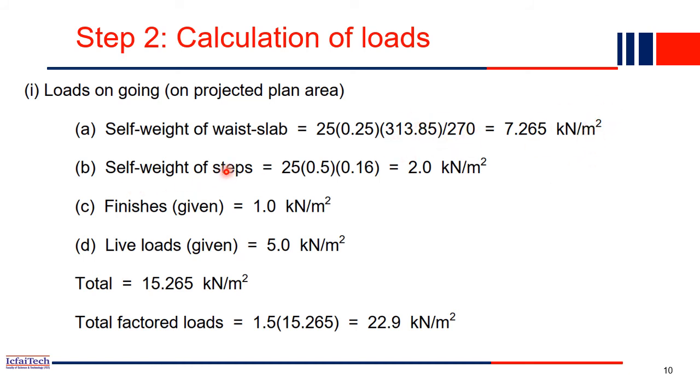Now self weight on the steps. So this is on the inclined portion, right? On the slab. So let me draw it here. So you have landing, and then inclined portion, and then one more landing, right? So this is the slab, waste slab, whatever we are considering it, this portion is basically this inclined portion, and then you have now steps. Okay, so this steps load also will be coming into the slab.